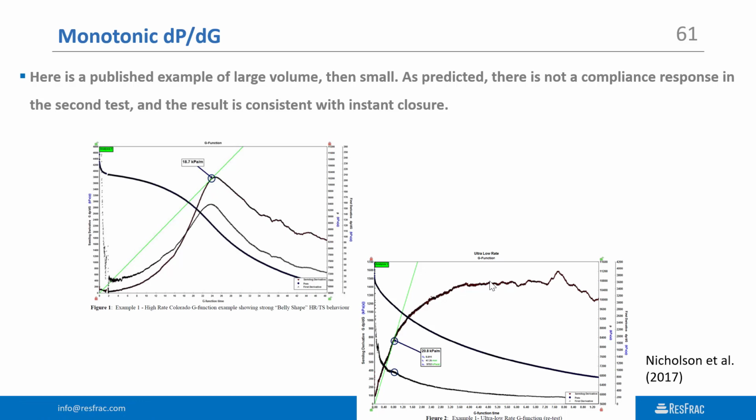Well, I've seen DFITs like this where they pump down the perf gun, and the act of pumping down the perf gun is creating a giant hydraulic fracture because they have a wet shoe, and then they fracture, and then they pump a little more, and you get a test that looks like this. In that case, pumping down the perf gun, that's the DFIT.